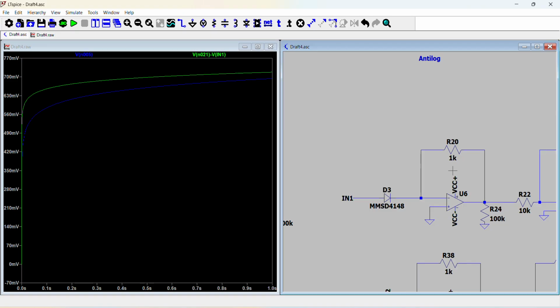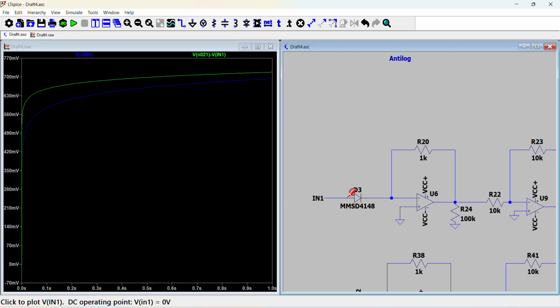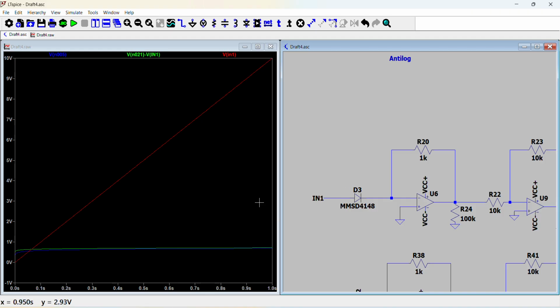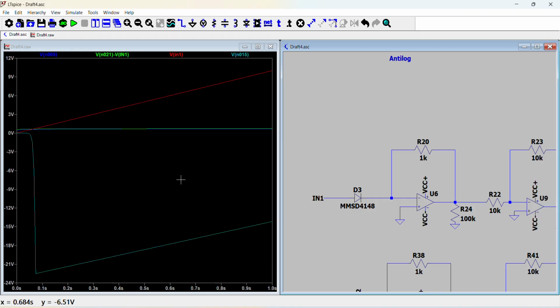And there's actually a problem with this, which is if you look at the output, you can see there's this drop and then something happens here. What happens here that destroys the output characteristic is that because it's exponential, there's a lot of voltage changes going on in the circuit, and the diodes can only support a certain amount of voltage drop across them before they start failing.